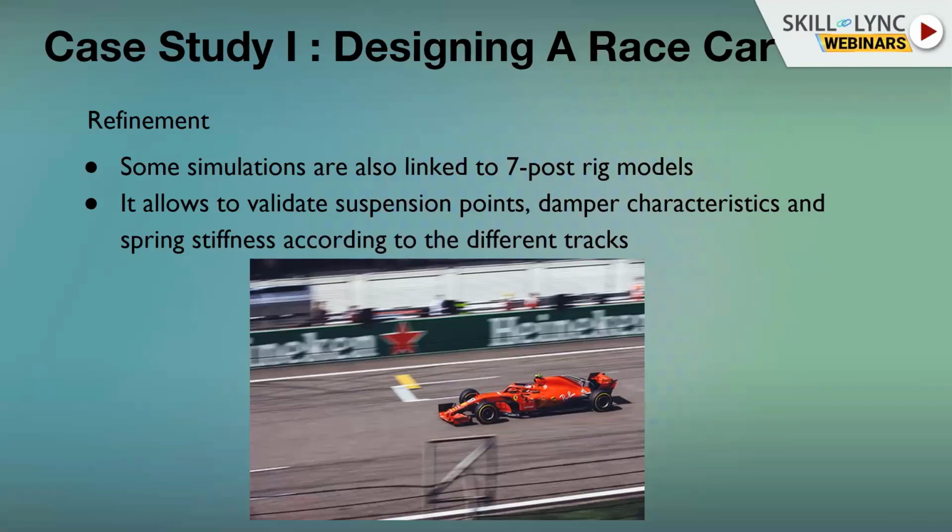And also it gives you the load you will have on your tire, and it validates the tire model you will use, because the tire model in the lap time simulation is the hardest to correlate, because the tire is not a perfect science. But it's important to know which parameters you are missing, or which parameters are not the most accurate.